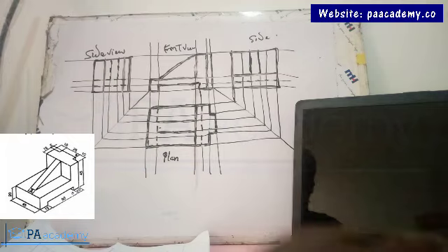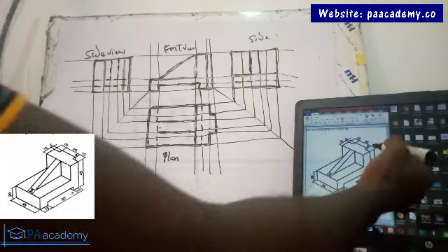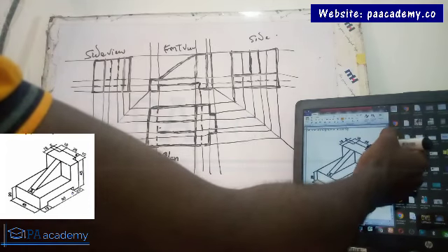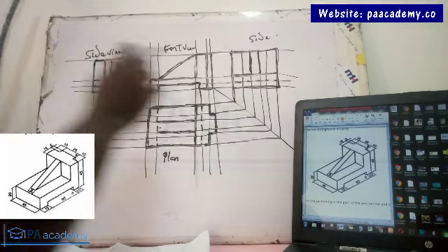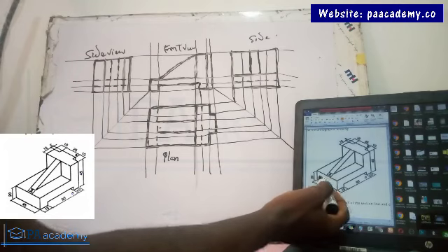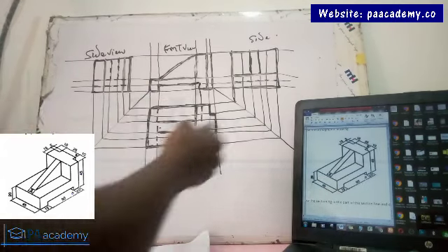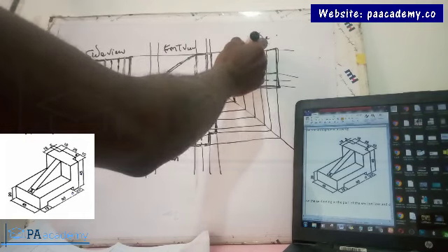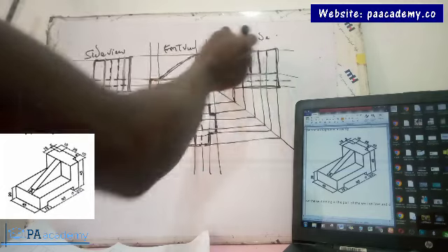All right, then there's also one more thing. Now, if you're also looking at it from this direction, you see this behind it. If you're looking at it from behind, this particular line, if you're looking at it from the other side, this line is visible. But if you're looking at it from the front, the line is not visible, but you have to indicate it in your drawing. So you indicate that with short dashes. So this is the line that represents that, this and this.